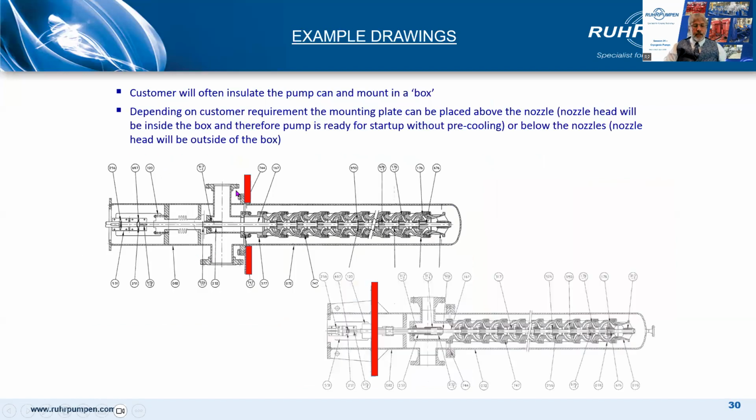I mentioned this earlier. The mounting flange can be here or here. This second position allows the whole pump to be installed in a cold box, which enables the pump to be always ready for startup.